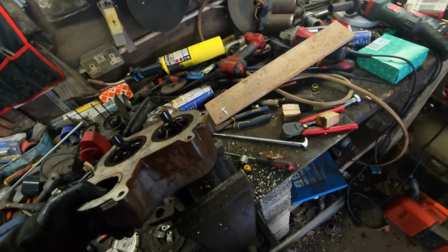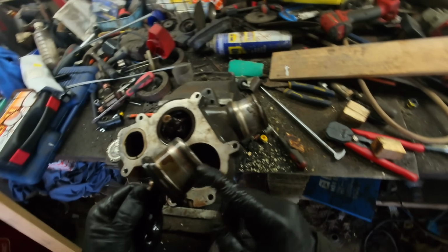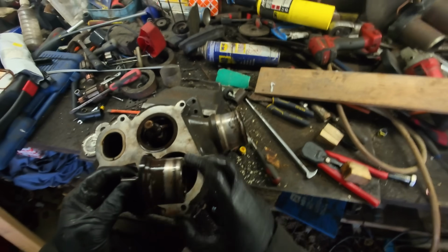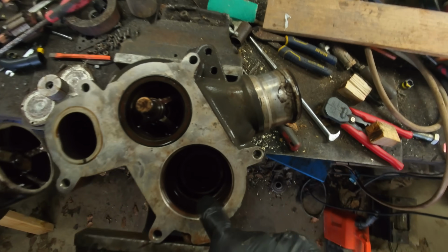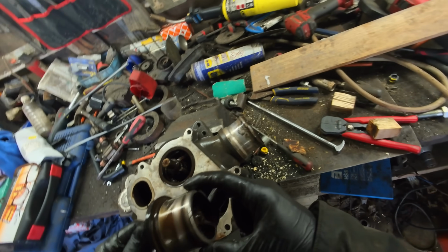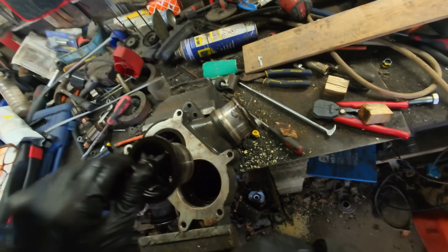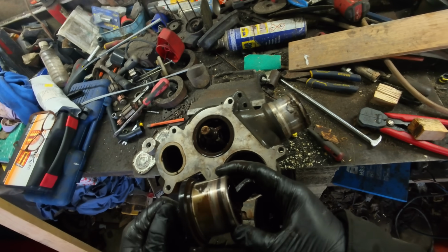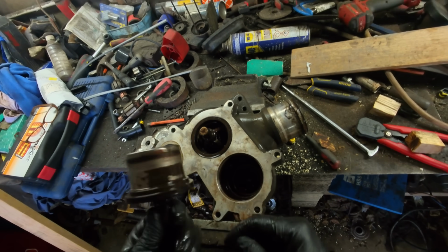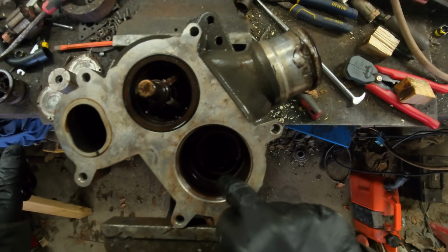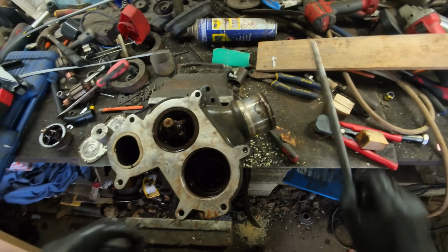So we've got two thermostats to change now. So it's not just as simple as changing the thermostat. If you can see this black band around here, this is where the seal that's inside here wears. And I find when this wears and they drop in and out this easy, this is why the truck starts running hot. So that's the easy part. Getting the seal out of here, that's the hard part.